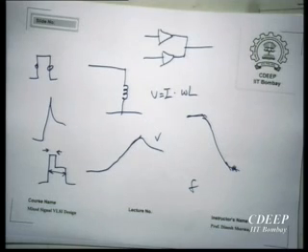However, one has to be realistic and there are a few disadvantages to this. So now stop celebrating. There are certain flies in this ointment. First, unlike most CMOS circuits, this solution takes static current. Because the circuits are analog circuits and they draw power all the time. Therefore, this is not a very good solution if you don't want high speed. So we simply declare that we are the Mercedes. And if you want a Maruti, go to Maruti. We sell you Mercedes. You want high speed, low power transmission of data, come to us.